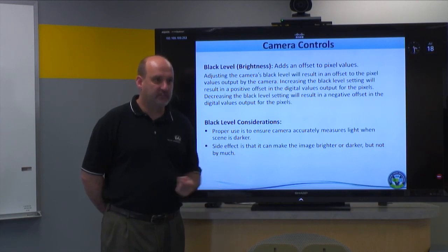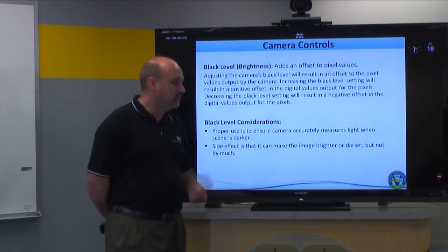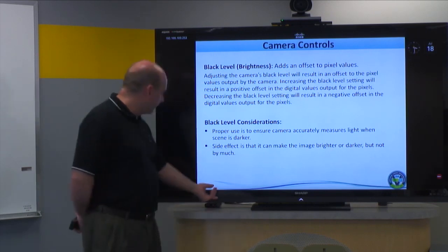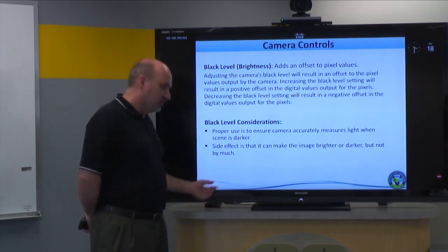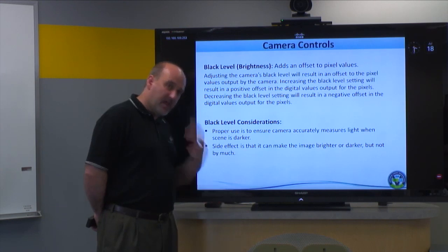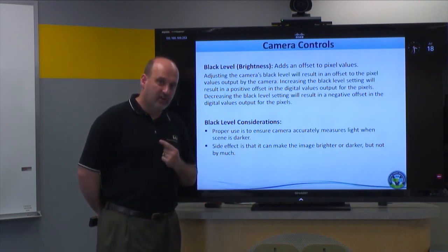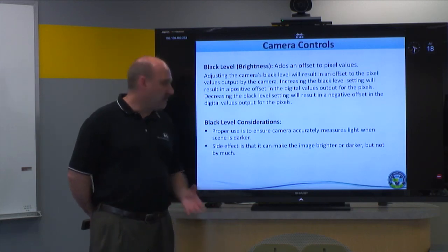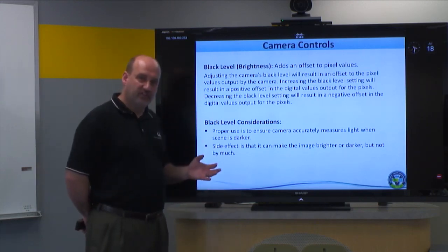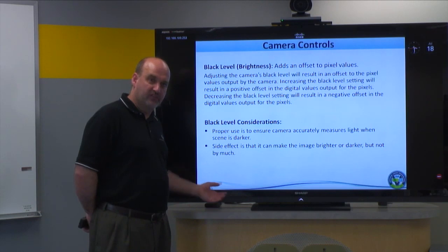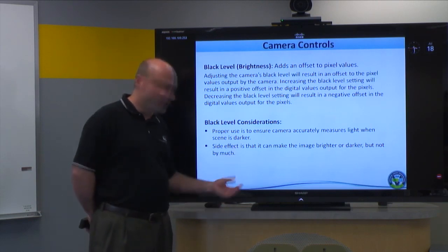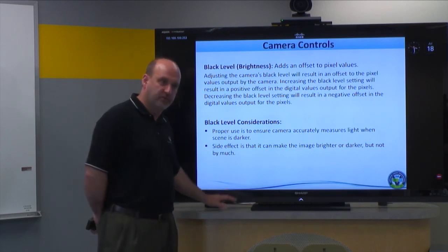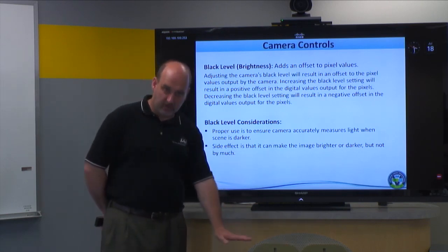In some cases, like if I set a camera up in this room and turned it around and started looking at things like the black frame around this TV, well, there's light coming off. This black frame is black to you and I's eyes, but yet there's a certain number of photons that are still bouncing and hitting it. So the camera will also see that, but in some cases, maybe I wanted that black frame to be black. So the offset gives the user the ability to adjust and say, ignore those few photons that are coming off. This really should be black, and set the right starting point in the image.